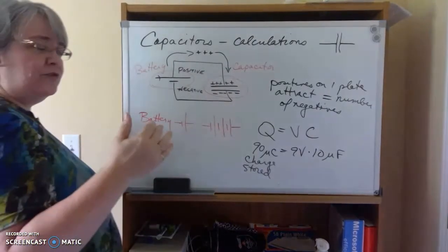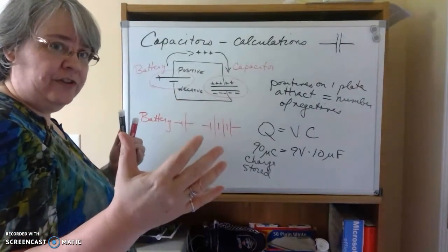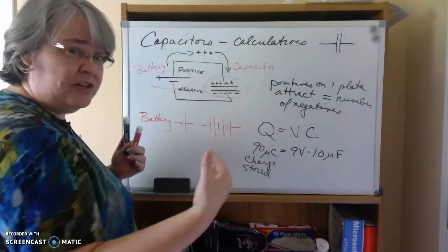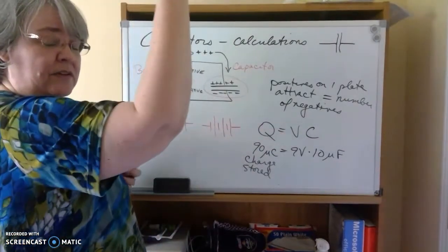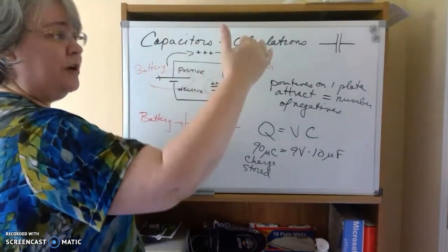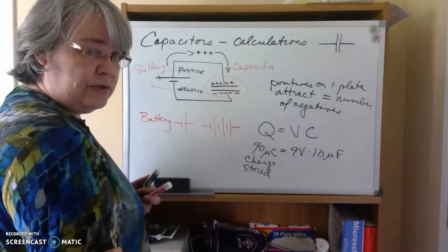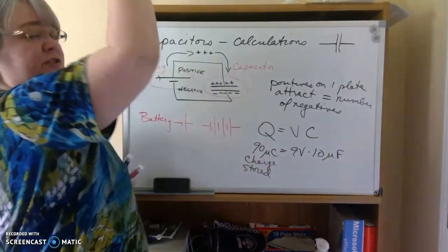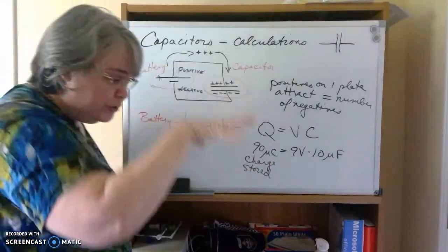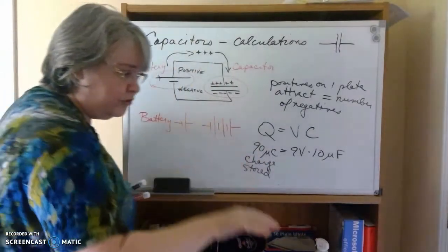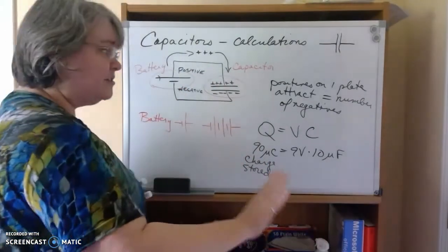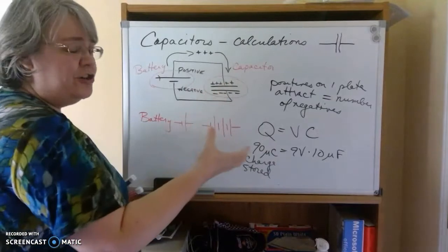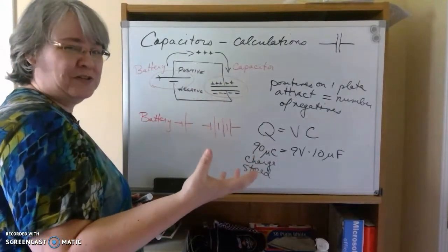And we think about voltage on those electric field lines. Remember, we had our equipotential lines where the top of the hill had the highest voltage and you come down to lower and lower voltages. Voltage is like a hill, right? A 9-volt battery is a really tall hill, and we're using the pressure from that voltage to push those charges onto the capacitor, because charges don't like to be crammed into a small space.